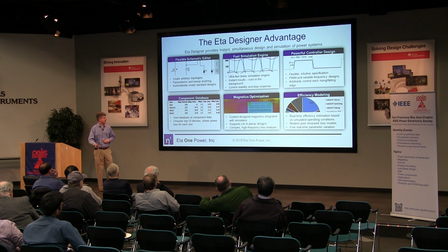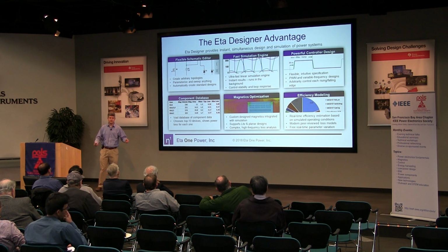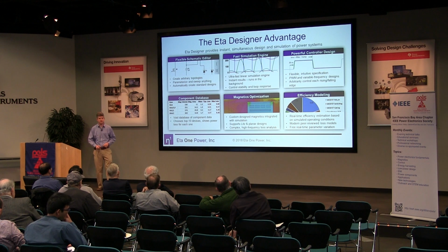Magnetics optimization, that's the topic for tonight. We can simulate custom magnetics. You can design your own core shape, or put in your own core shape, put in your own windings, slits, wire, etc. I'll get into this in a lot more detail and find all the losses associated with that in the context of that power converter, not idealized waveforms, but that power converter.